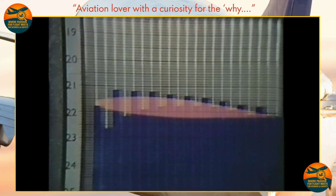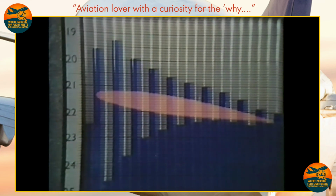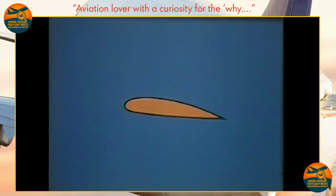The manometers attached to the upper surface rise, indicating a considerable drop in pressure, while those attached to the lower surface fall, indicating a rise in pressure. And it's this difference between the pressures over the upper and lower surfaces that gives the wing its lift. In fact, the pressure pattern looks like this, with the pressure at any given point acting at right angles to the surface at that point. The pressure difference is greatest where the curvature is greatest, least where the surface flattens out.